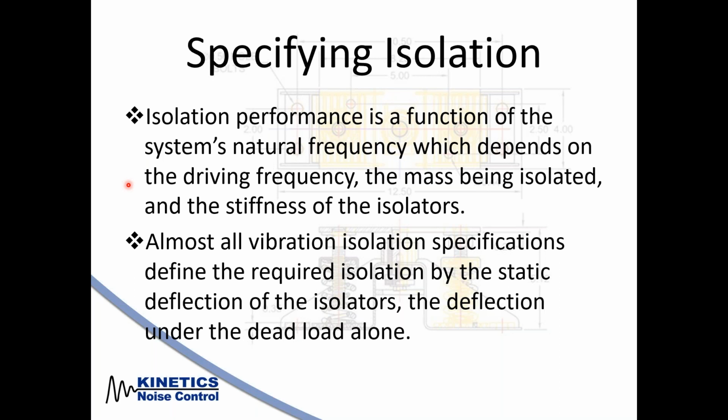The isolation's performance is actually a function of the system's natural frequency, which depends on the driving frequency, the mass that's being isolated, and the stiffness of the isolators. Almost all vibration isolation specifications define the required isolation by the static deflection of the isolators themselves under dead load.